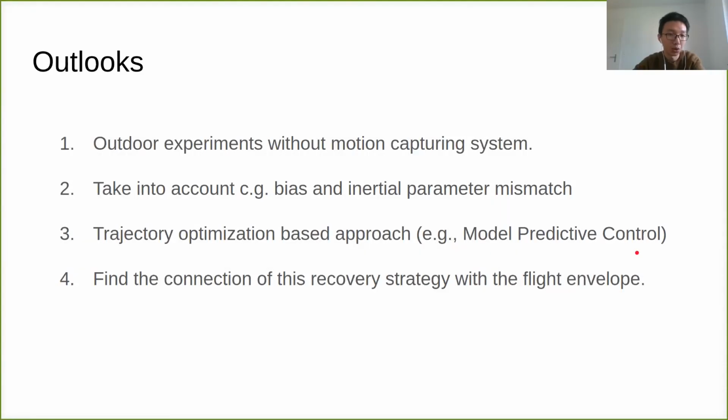Now come the outlooks and recommendations for future work. First of all, we would like to conduct outdoor experiments without a motion capture system. Secondly, we want to take into account the center of gravity bias and the inertial parameter mismatch. Thirdly, since our approach is not an optimization-based approach, perhaps we can find trajectory optimization-based methods to further improve the recovery performance, such as model predictive control. Last but not least, perhaps we can find a connection of this recovery strategy with the concept of flight envelope protection.